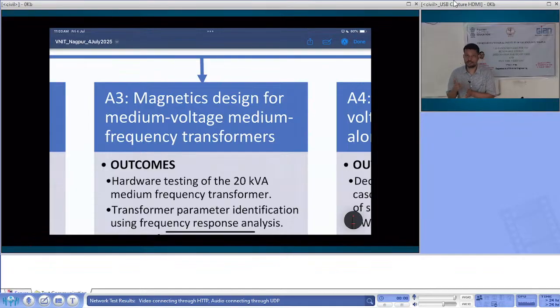Practically, a square wave may saturate the transformer. In that case, it would start drawing larger input current, which are harmonic currents, which would create a drop because of the cables and line impedances, which would change the shape of the output voltage. So in reality, it would not be a perfect square, but somewhere in between. If it's not saturating, then it would be square.